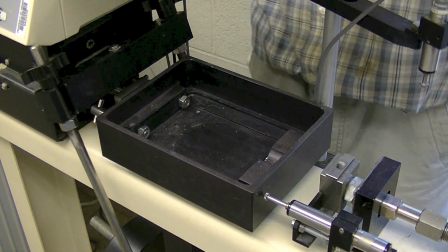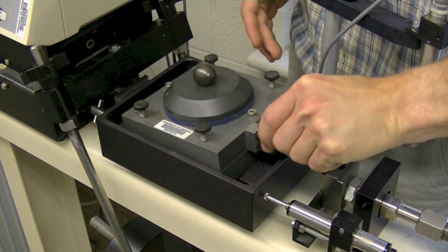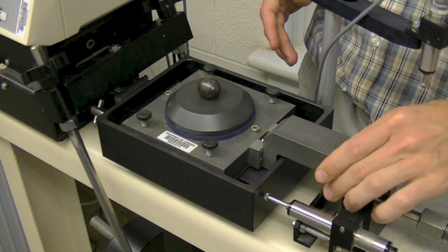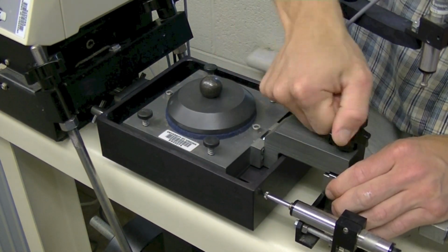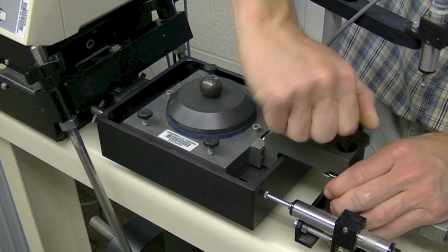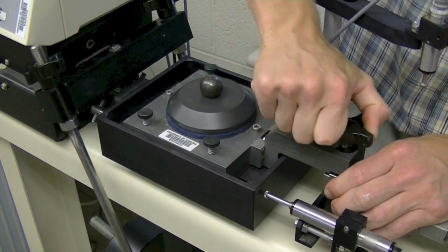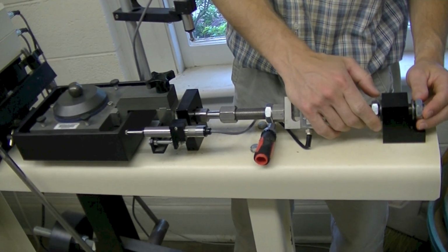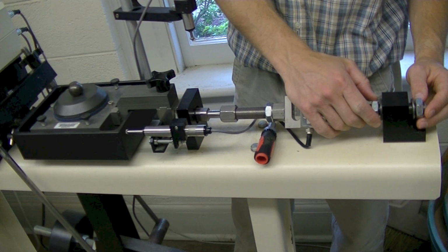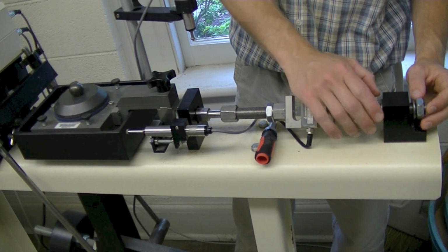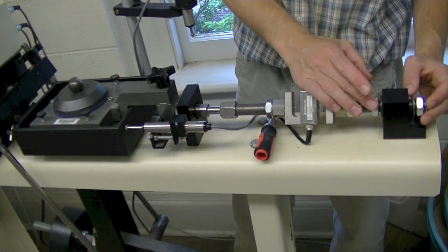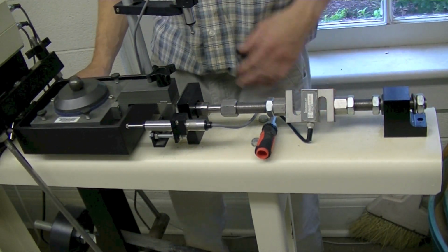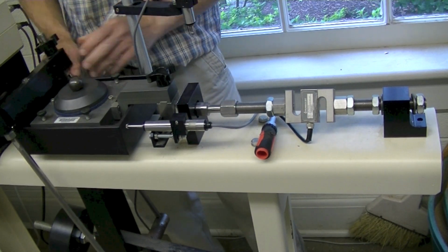Place the shear box into the assembly so that the bottom half connects to the geared jack. This allows the motorized jack to move along the shearing axis or bottom plane. Screw the large vertical screw into the bracket on the opposite side of the geared jack. This fixes the top box. Note that this bracket requires a measuring device, a load cell, to provide opposing force to the upper half of the shear box. It is best to unscrew the two nuts on either side of the abutment at the end of the transducer arm. This gives the assembly some slack while everything is being set.